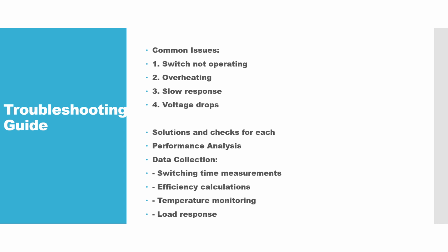Data collection, you must collect data. When you apply load, what is the voltage, what is the current? When there is no load, what is the voltage, what is the current? You now analyze those data collected to know what you should do, and which threshold you should not exceed. Switching time measurement, like I told you, we must be able to measure accurately.